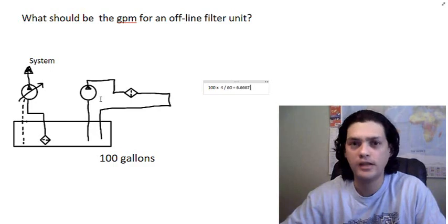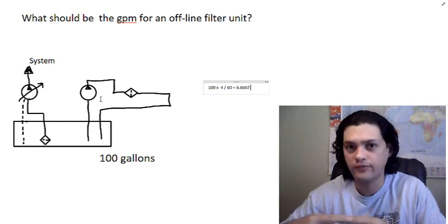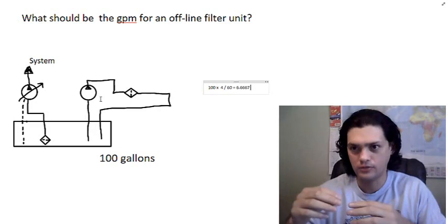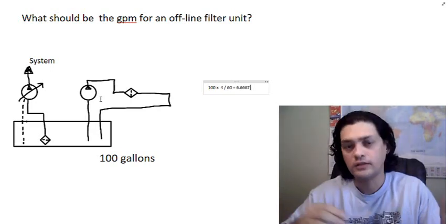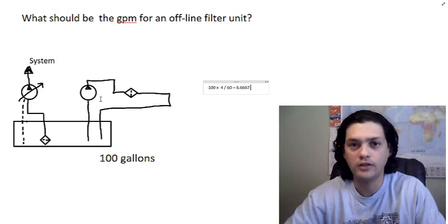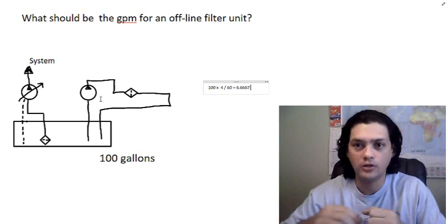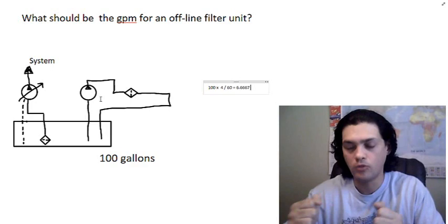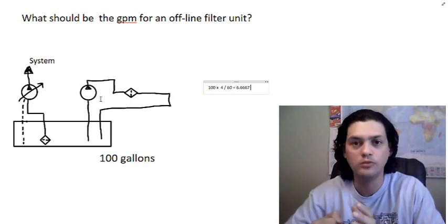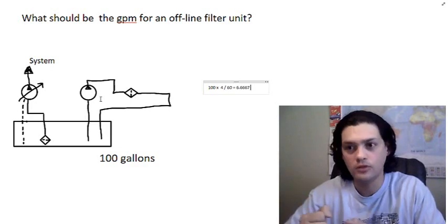So when you have contamination accumulating, it takes more force for the solenoid to shift the spool. Contamination creates more force, it's more work for the solenoid to move. As it gets older, it loses the force to keep shifting, and you have to change solenoids.